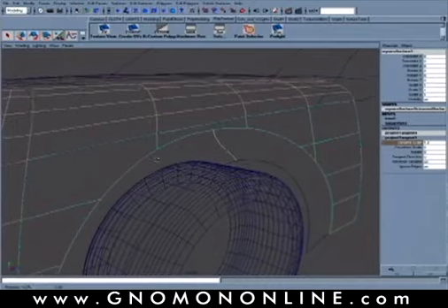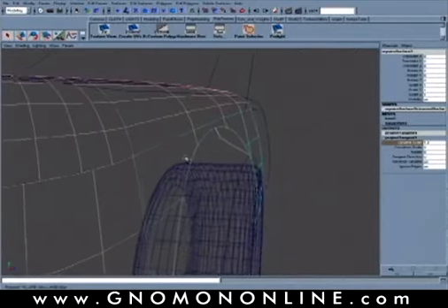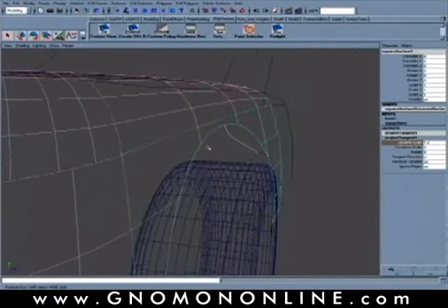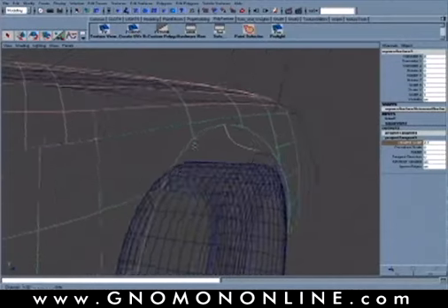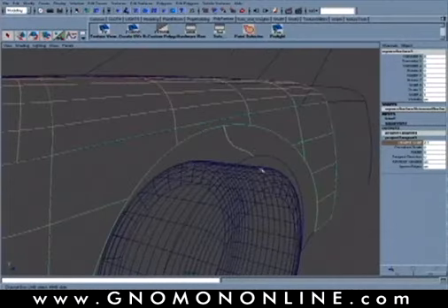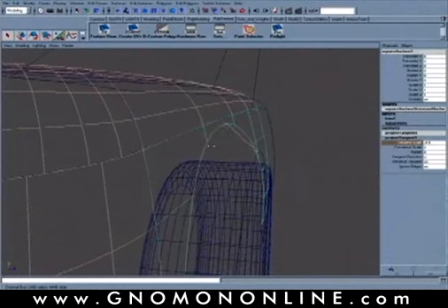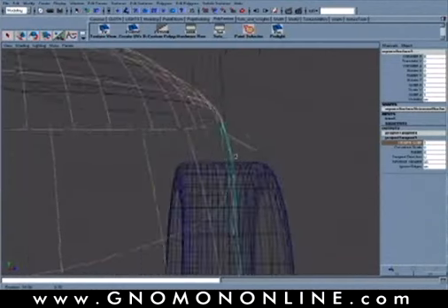Okay, so this one's a little more critical, and we're really designing how that rim section is going to integrate across here, or how that fender is going to fly down. So if you want to have a real smooth integration, you want to give a little more tangency, but also a little more lead gap between these two. Or if you want to make it a little tighter so it's really a quick turn as it goes from one place to the other.